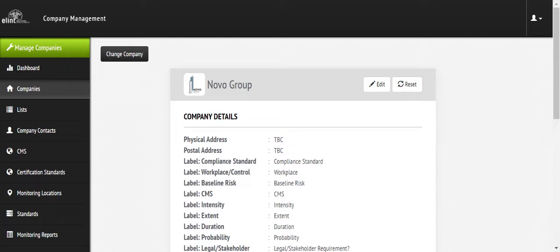What we've also seen as a benefit of using the system is that even if the contract doesn't require a health and safety file, the discipline is there, so that we still use the health and safety file principle to make sure that they comply with the Occupational Health and Safety Act, Section 8 specifically. So that if something happens on site, they have all the documentation, they have done their checklist, and the discipline is there. People are not just using a ladder and not doing a checklist. They're actually doing their checklist because it's now part of the way they do business.